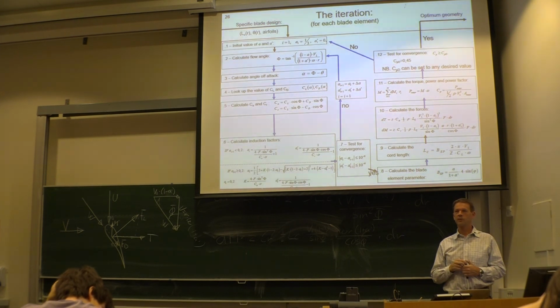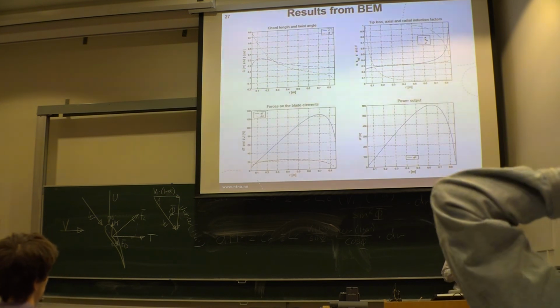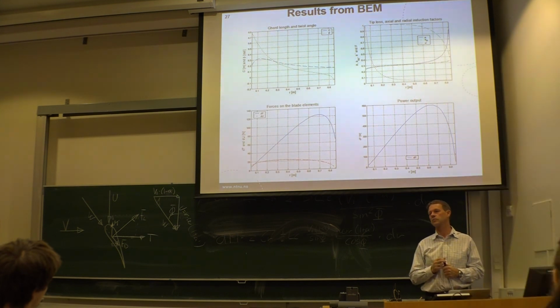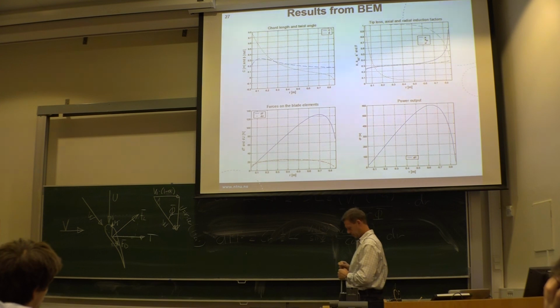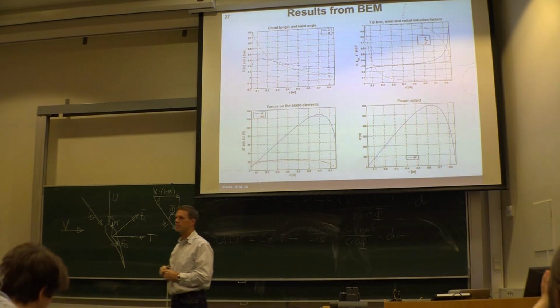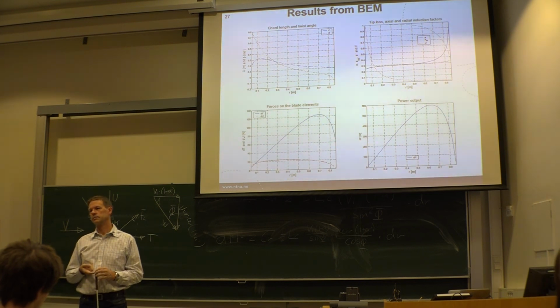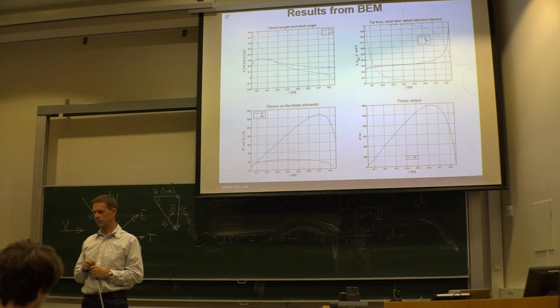That's the blade element momentum method. That's how it works. And out from this, you're able to calculate the forces, the chord lengths, the power output, and so on and so on. So that's the algorithm you're going to write in your program.